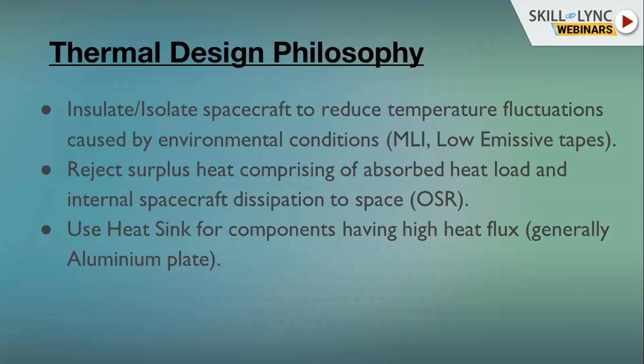Then you need to reject any excess heat in the system. For that we use OSRs, which are optical solar reflectors, also called radiators. Now these radiators, like I said, have a high emissivity in the IR spectrum and low solar absorptance.